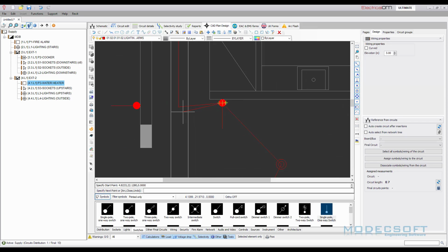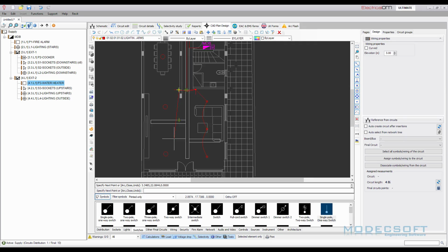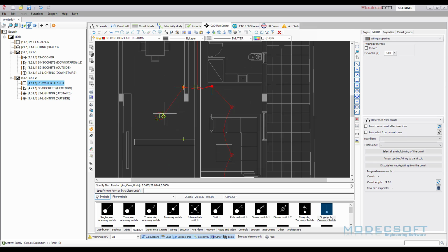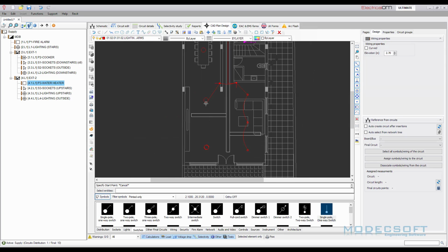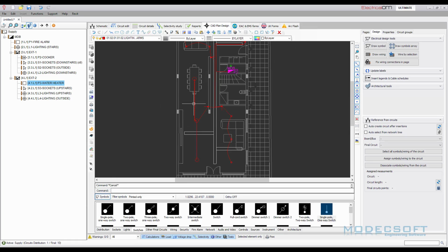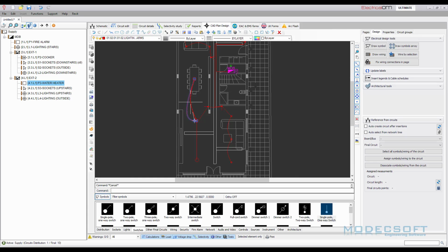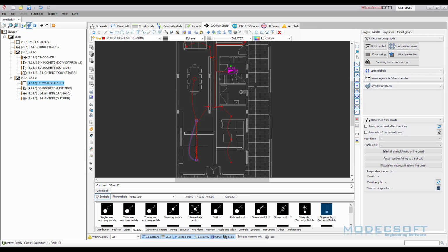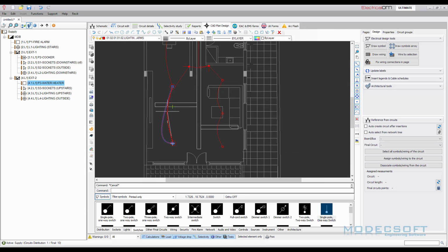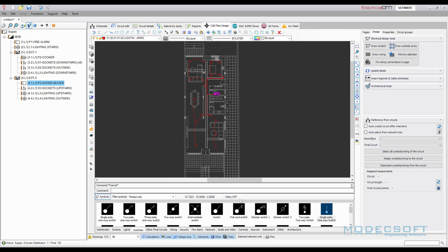And from this one, we can go back to this one as well, which we consider that controls mainly these 3 lighting points, which we are going to connect them together using the wire by selection for this case, 2.7 meters. And also we can double click and change whether it will be a curve or not, the wiring as well. So in this case, we managed to create some simple wiring for our lighting points.